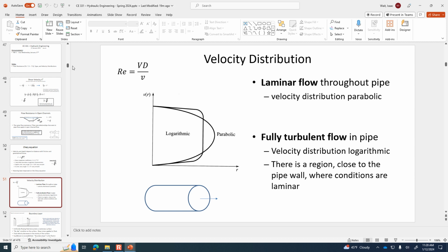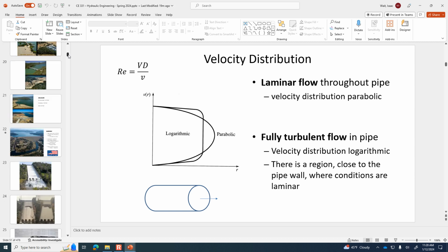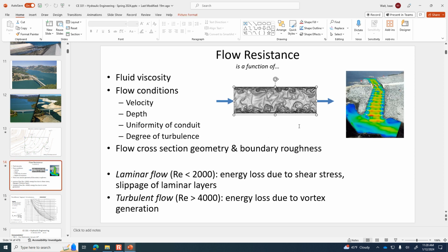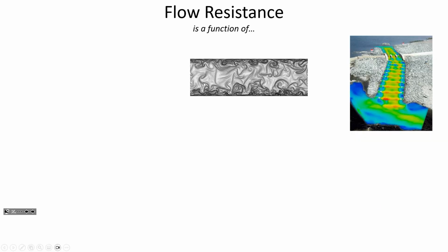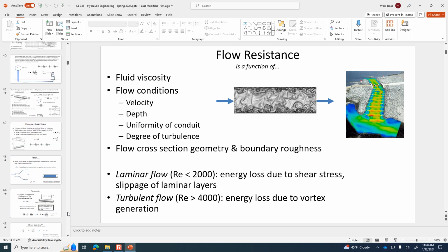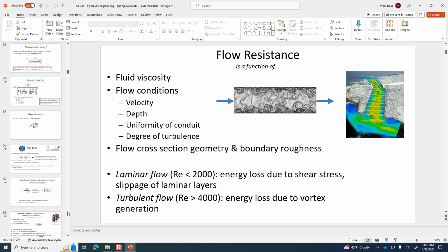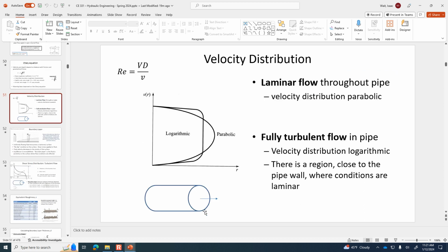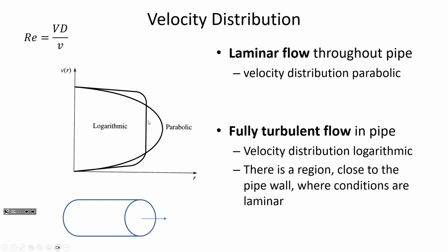There was a slide that I showed you on the first day that kind of illustrates this point that there's a lot of random variation inside of a pipe. So this is showing that at the center of the pipe, the water is flowing more freely, that it's less under the influence of the side turbulence. And so the average velocity distribution is more flat in the vicinity of the pipe. Is more flat as you get into higher flow velocities.